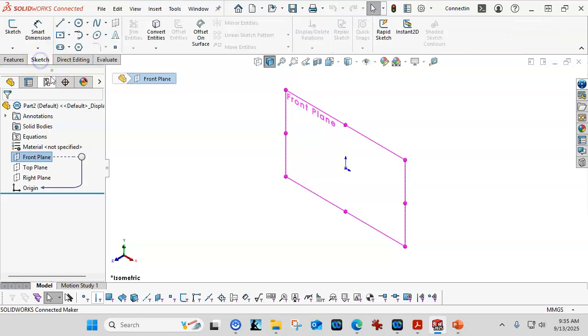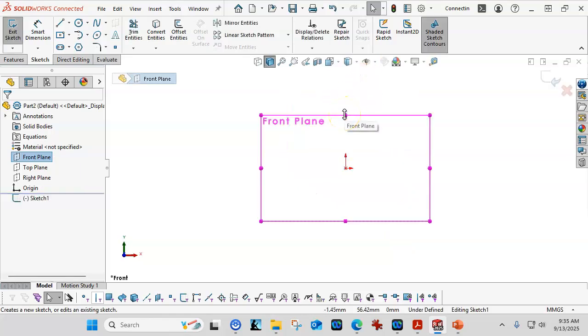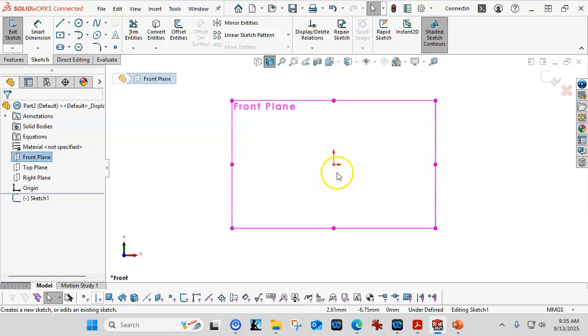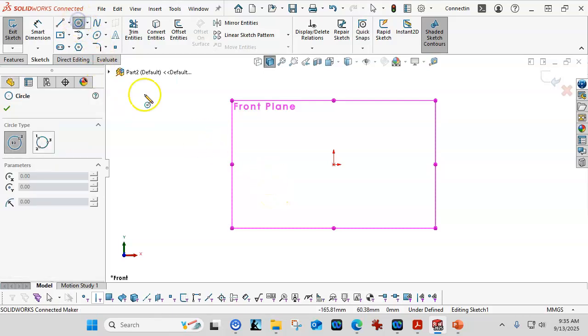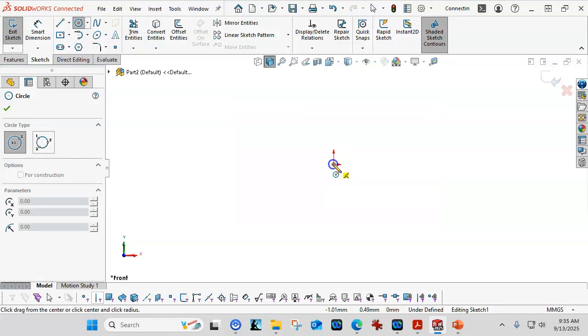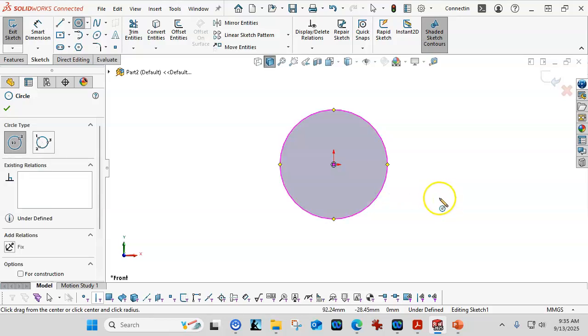So the body. Did I get it? No. Okay. Make sure that I'm clicking at least one of the sketches to get into the red origin with the confirmation corner. So the circle, and it is showing us a radius of 43.